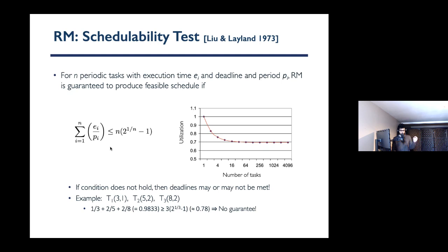Okay, just to recap, we talked about rate monotonic. We talked about the feasibility of it. We also said that it's optimal for the class of static schedulers. One thing I want to note is that it should now hopefully be clear what static schedulers are. As you saw with rate monotonic, we just gave a priority to T1 and it wasn't changing over time.